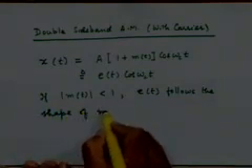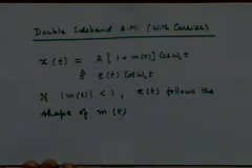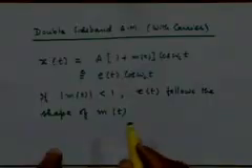But wasn't that always the case? No. In the DSBSC case, the envelope is proportional to the modulus of m of t. What we would like to have is the envelope be proportional to m of t itself. And of course, why we would like to have it is another issue which I will come to in a few minutes. Right? How does it help us is something that we have to still discuss, but I just want to point out this interesting fact which was not available to us in the suppressed carrier modulation, because there the envelope was proportional to modulus of m of t. Here we are making the envelope proportional to m of t, right?